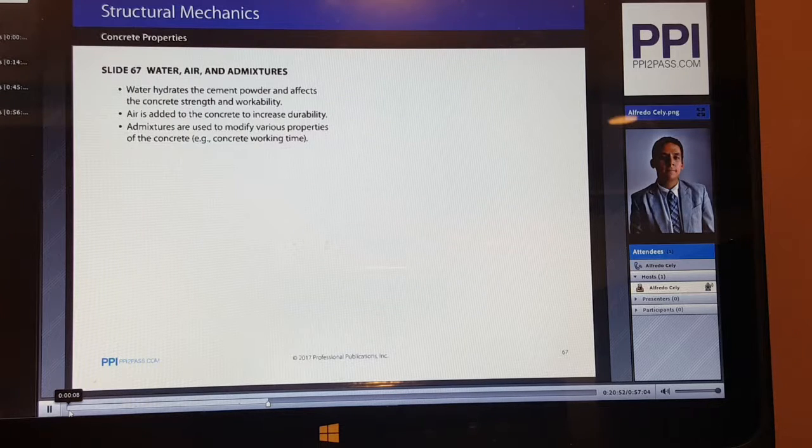1 ton, 2,000 pounds mass of water has a volume of 240 gallons. Water used in concrete should be potable in order to conform to ASTM C1602 and have no pronounced odor or taste. And the reason that ASTM C1602 calls for potable water to be used in concrete is to make sure that the water does not have any additional chemicals or additional minerals that may interact negatively with the concrete chemical reaction.